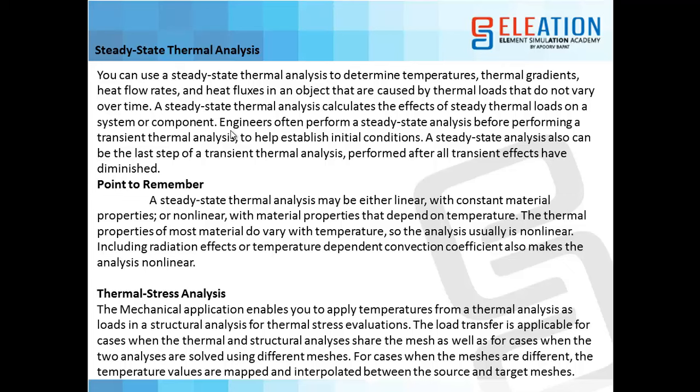So a steady state analysis also can be the last step of a transient thermal analysis, performed after all transient effects have diminished. Points to remember: a steady state thermal analysis may be either linear, with constant material properties, or non-linear, with material properties that depend on temperature. So we can give two types of inputs in steady state: a material having constant properties, or a non-linear material with time dependent properties.